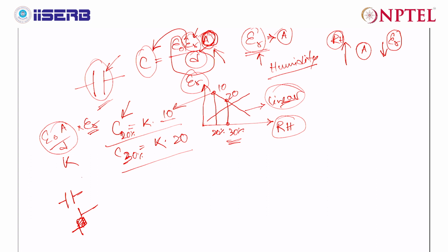Once it is based on deflection, usually force can lead to a deflection of an electrode. So you can detect force in terms of capacitance. You can design the entire sensor in a way that one electrode is fixed and the other electrode is deflecting.